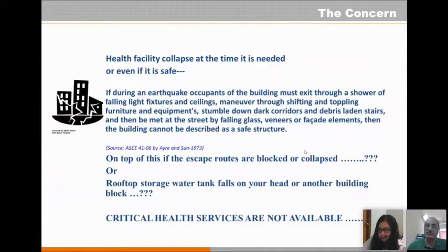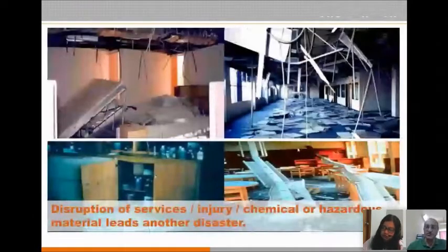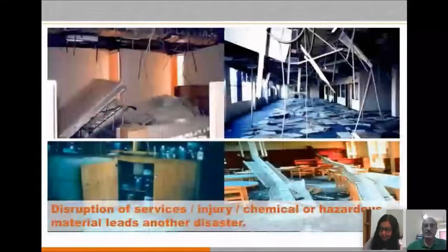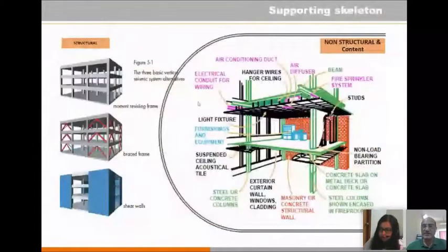should also be given proper consideration, because normally we have seen after any seismic event, particularly in hospitals, your structure may be standing perfectly, but the non-structural elements, in the form of false ceilings and furnishing items, fall down, and appendages and claddings fall down, and as a result, more hazard results from the failure of the non-structural elements.